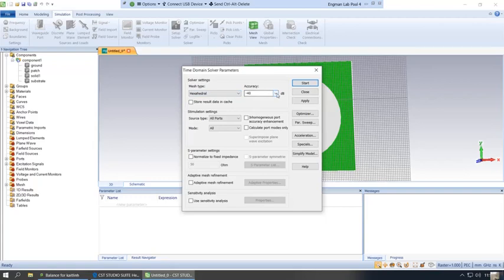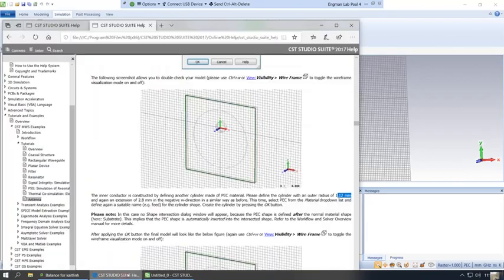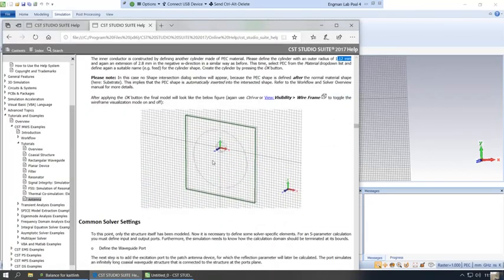So usually for this lab, we will usually do simulations between -40 and -50 dB. So the further down you go, the more accurate it is, but the more time it will take. So we're going to leave it at -40. And then very often we will do adaptive mesh refinement. I'm curious if they have us do it in this tutorial or not.